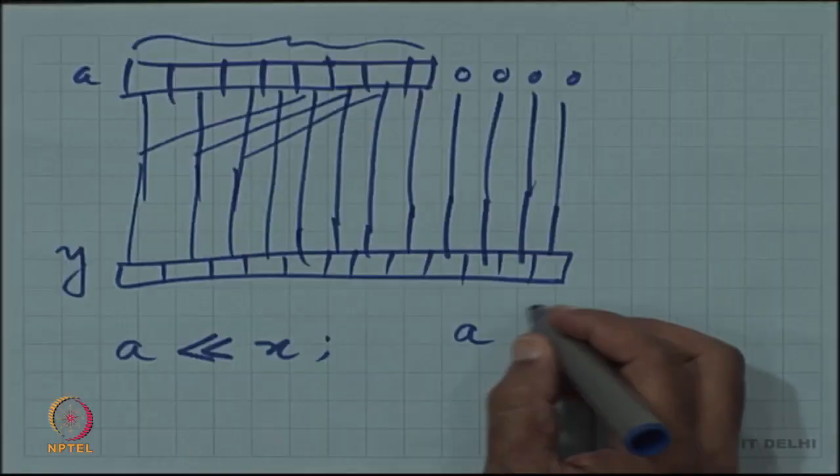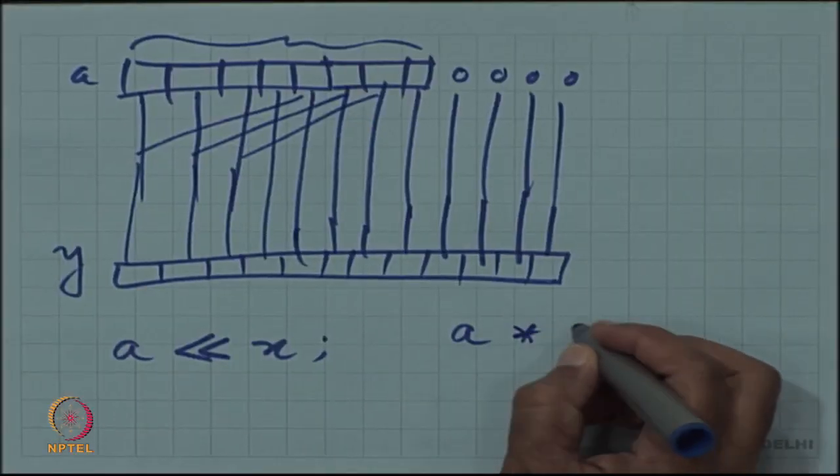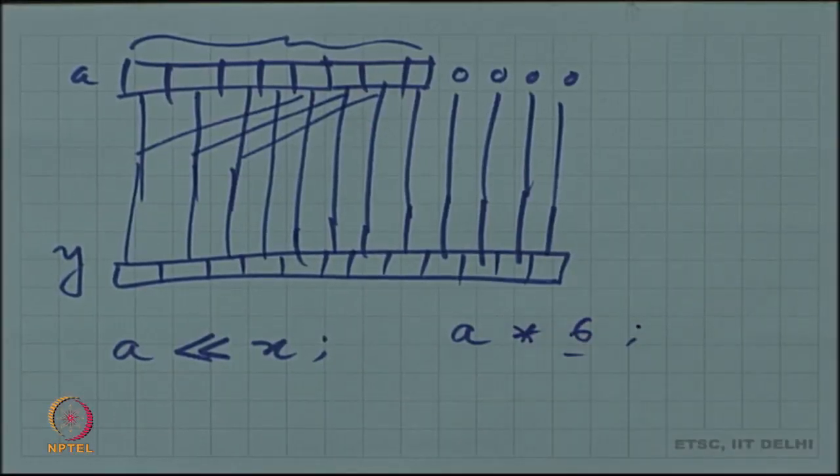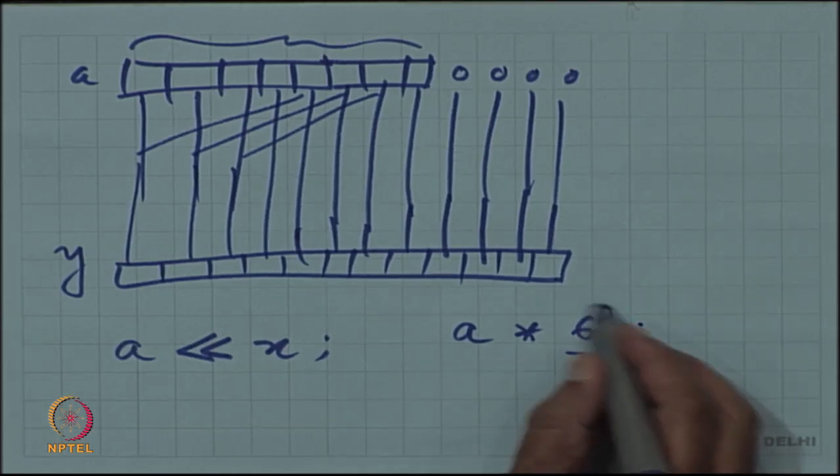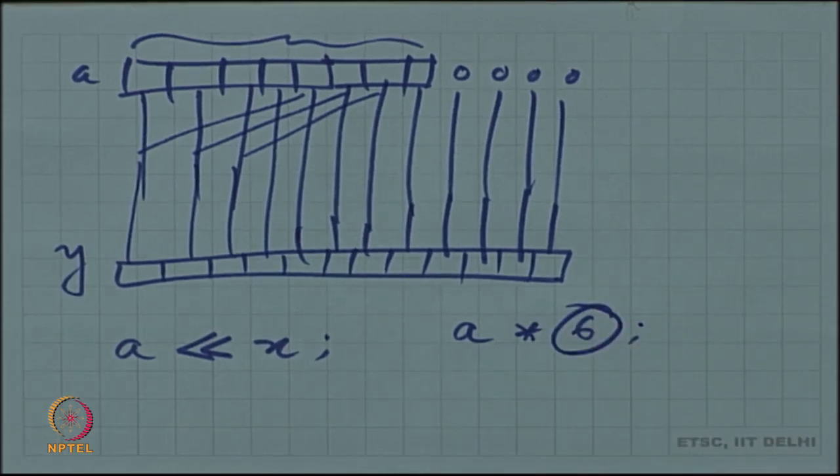If you had this kind of a multiplication which is not a power of 2, nevertheless it is realizable in terms of an adder, which would be enough to perform that kind of multiplication. So, I should be looking for such opportunities. This is a constant, so a lot of static analysis could be done to find out what kind of hardware I really need, what is the cheapest hardware with which I can perform that computation.